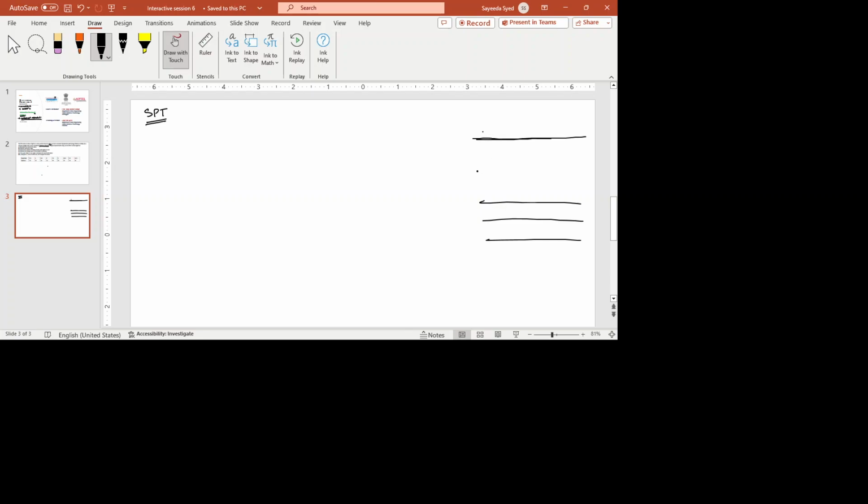Why? Because, for example, if I have a dense sand with good properties here, and I build a foundation here, the load on the foundation is carried in the form of a bulb through the soil. If this bulb is going through multiple strata, we need to be sure that the settlement in all these strata is not excessive.